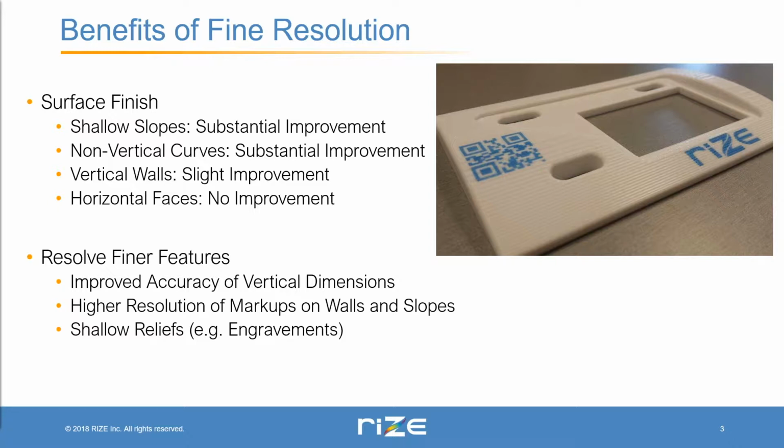So essentially places that have very visible stepping that results from the layer lines being resolved in a way that you can see the separation between each layer. So this would happen on any surface that is close to horizontal but not quite horizontal. It's not so much an issue on surfaces that are close to vertical but not quite vertical. It's only those that are close to horizontal.